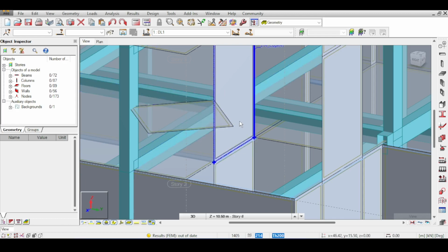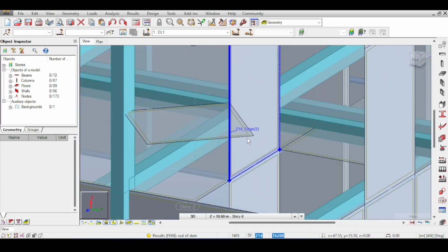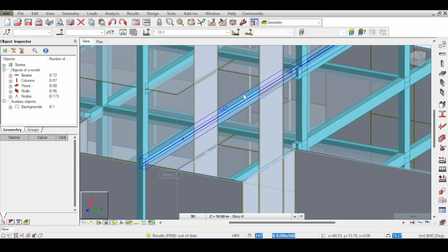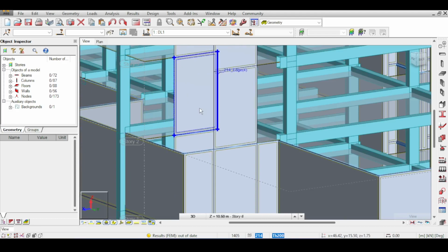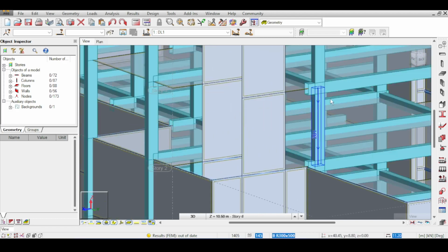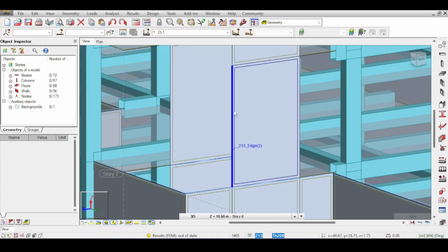I would have to cast it quarter height and then have some detailing in steel here, and then cast the rest with the beam to have a rigid joint. It's kind of iffy. It's possible. I will leave this empty, and I want you to tell me what you think in the comments. Should I go for the cantilevered beam, like a beam flying all the way out, carrying the landing? It's kind of iffy in the field, because I would have to make sure that there is a rigid connection between this and that.